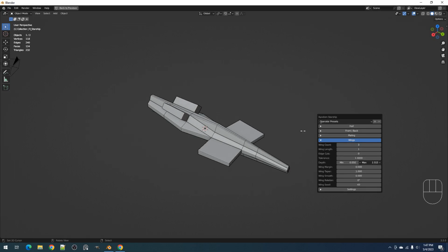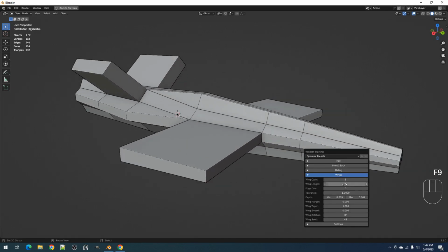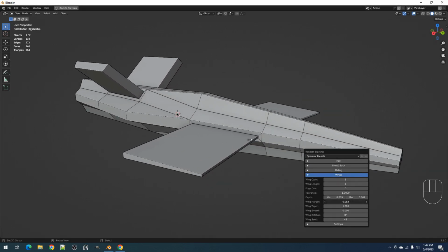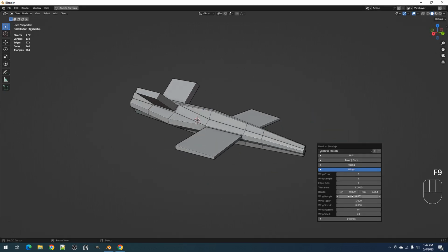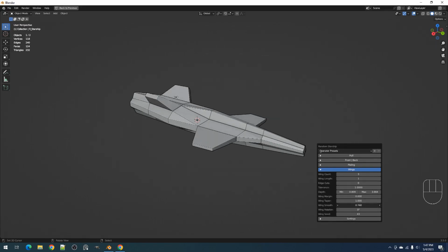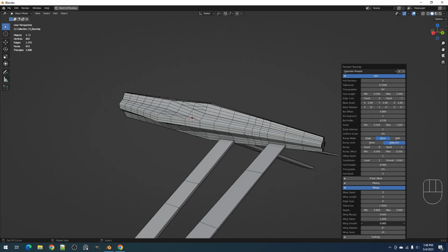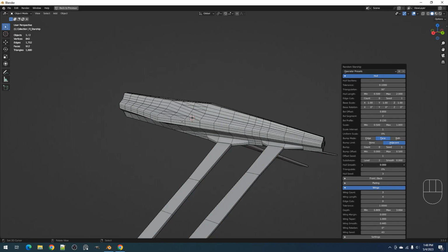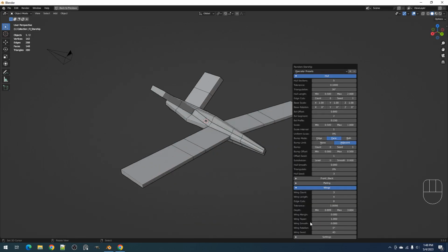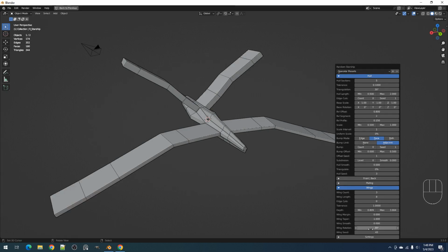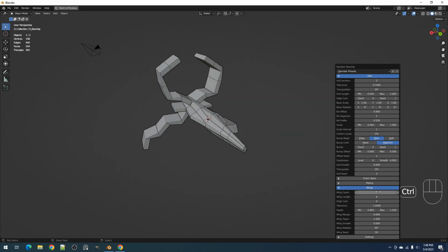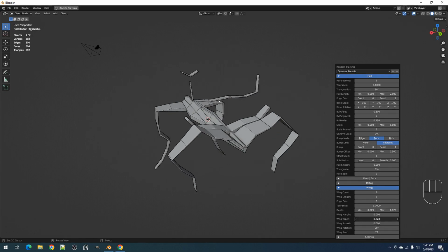The depth property, with its minimum and maximum values, determines the length of each extruded wing segment. The wing margin property sets the margin for the face the wing is extruded from. This is an extra control for the size of the wings. The wing taper property scales or tapers the wings. The wing smooth property smooths the wings since the wings are not affected by the hull smoothing. The wing rotation determines the rotation of the wings per segment. Use this to come up with really weird or alien looking ships.